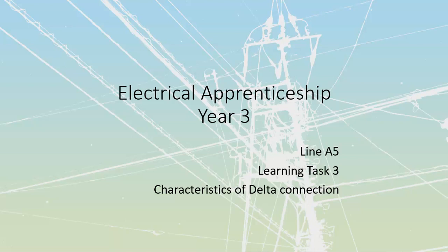If somebody has a high voltage connection coming in, like one of the plants that one of my brothers works at as an instrumentation electrician, they come in at 25,000 volts, 3-phase, but then they drop that down into multiple smaller services, 600, 347, 120, to distribute to some of the other components on site. Sometimes, as they come off of that, I'll just draw it over here, 25 kV slash 14.4 kV line that they're coming in at.